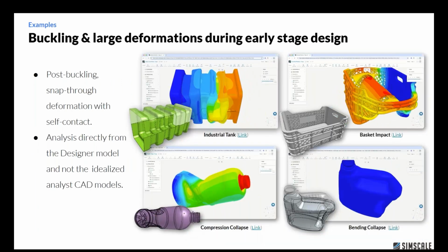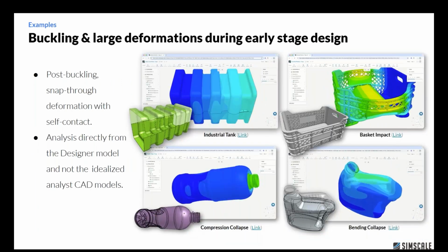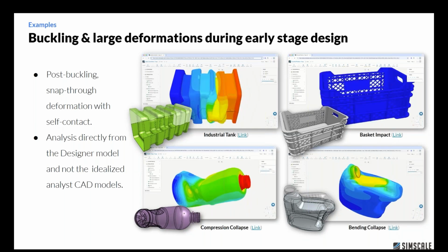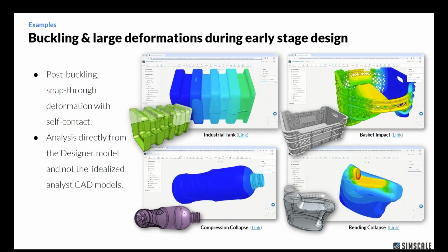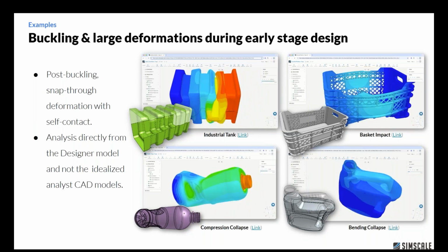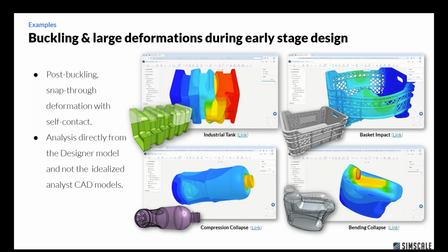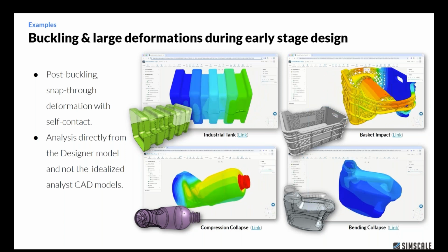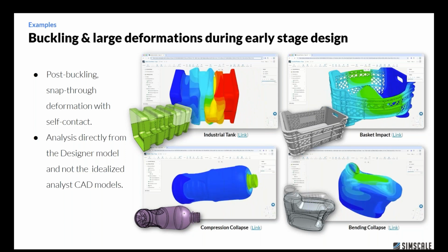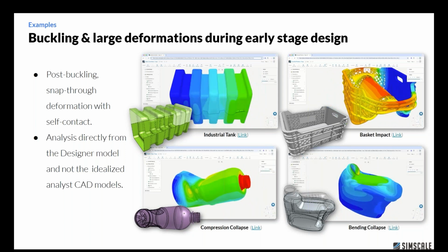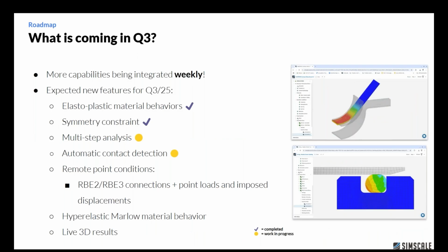And we can now really do large studies with not only a single part, as shown here, like nonlinear buckling behavior, but also very large assemblies with a much simplified approach to contact definition. As we have seen, we have a body-to-body, a volume-based contact definition, so you don't need to select the actual contact faces anymore.